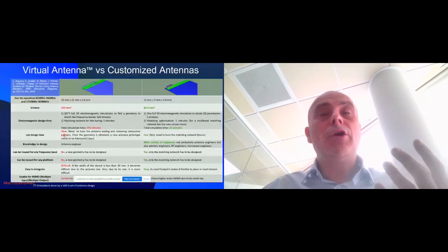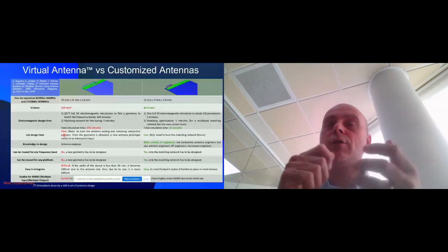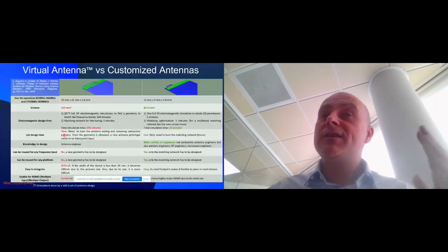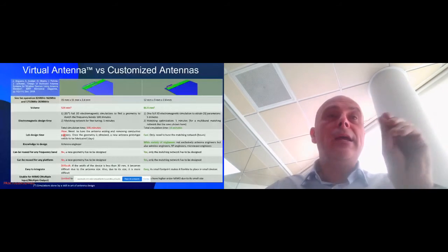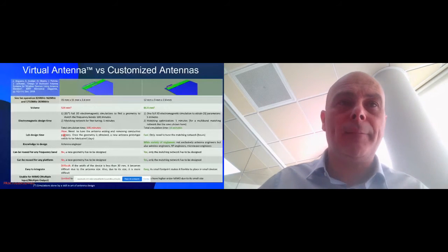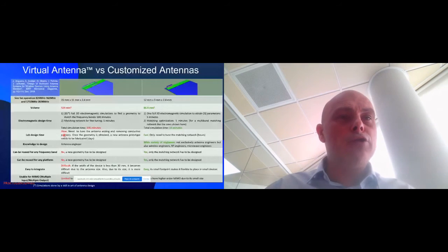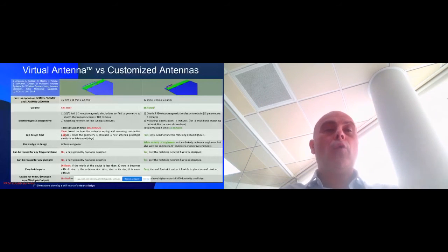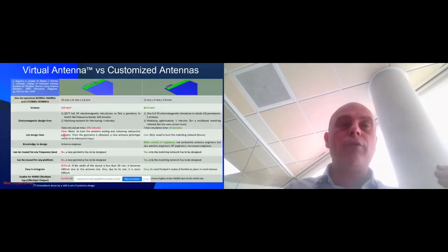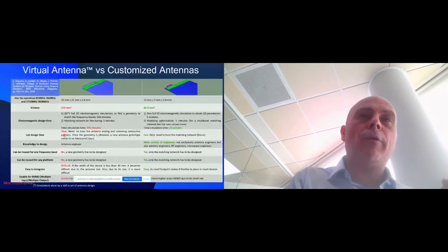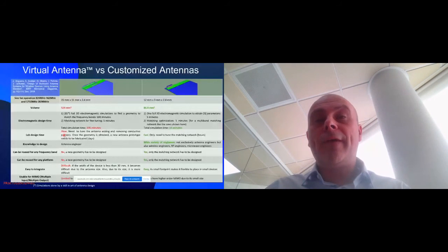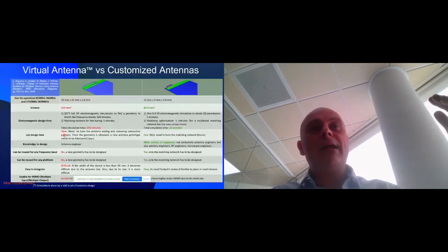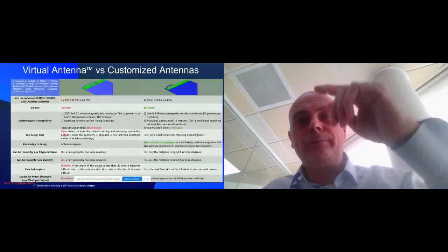With antenna boosters, you don't need that, because if the customer needs to make some changes on the PCB, we have the same antenna booster. It's off-the-shelf. The only thing we need to do in a fast way is to fine-tune the matching network. It is very flexible. Also, reuse at other frequencies, as we told before. We receive many projects changing the frequency. We couldn't reuse our own customized antennas. We needed to do a new antenna from scratch. With the antenna booster, we can reuse the same antenna booster and design a matching network in a systematic and automated fashion.